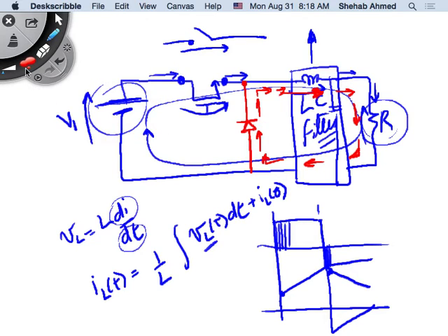So what happens when the diode starts conducting, in this case, because the switch opened? How about when the switch turns on again? So when the switch turns on again, what is the voltage that I put here? What voltage does this node see when the switch is on? 5 volts, exactly. So V1, or 5 volts, this positive voltage.